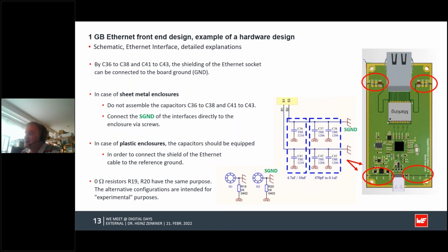You can connect the digital ground directly to the housing, but not on the PCB here. Then you have a much higher immunity against transients which are coupled in from the cable to the port, or from the other side, depending on how long the USB cable is. You can separate transients which are coupled into that cable.